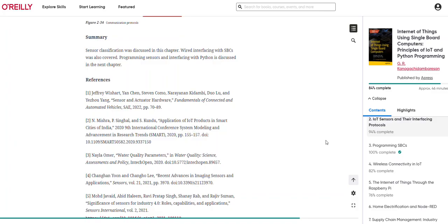Logic level shifters or voltage dividers are often needed to match levels safely. So we've got to make sure that all these connections match up. If they don't, we've got to find something to get it right, and level shifters can do that for us.